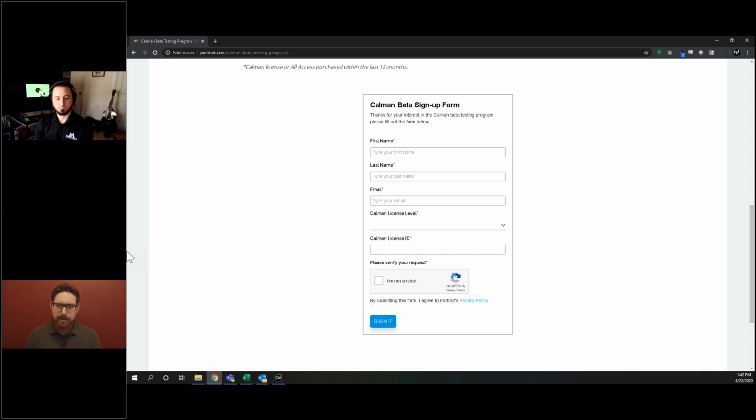We added new intelligent meter averaging, because one of the problems with the way it was implemented in Calman is we had fixed exposure times. So you could say, I want an exposure time of 1 second, and it would do that for a bright patch and a dark patch. For the bright patch, it was kind of overkill, and maybe on the dark patch, it wasn't enough.